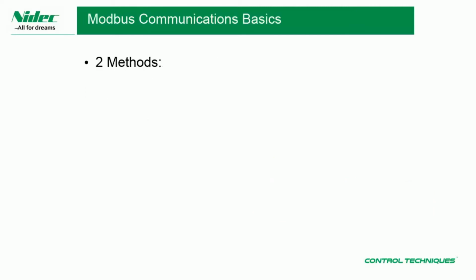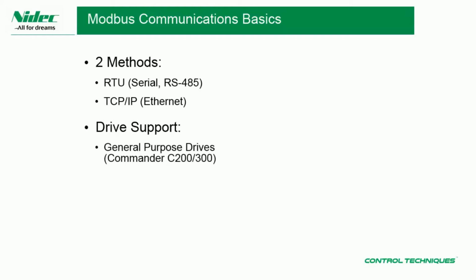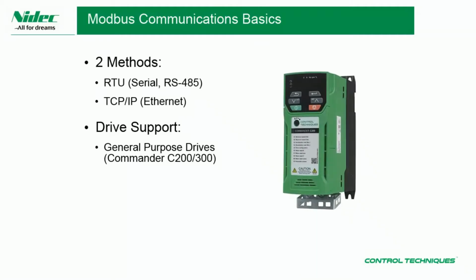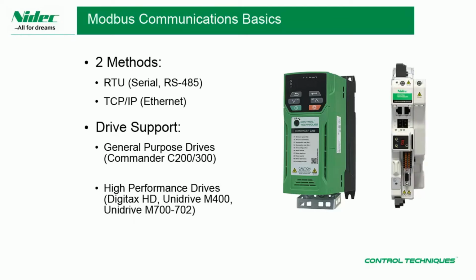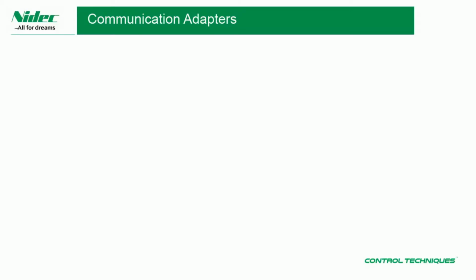The Modbus communication protocol provides both Modbus RTU for serial RS-485 based communications and also Modbus TCP/IP for Ethernet communications. Control Techniques general purpose drives, such as our Commander C200, along with our high-performance drives, such as our Digitax HD, can both be accessed using either serial or Ethernet Modbus communications. Additional communication adapters may be required for Modbus communication.